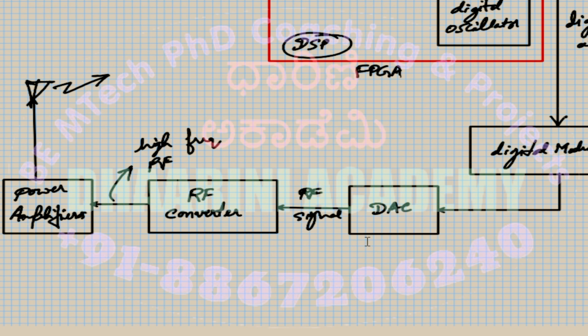If you recall, OFDM is orthogonal frequency division multiplexing, wherein you send multiple symbols, in the case of digital, over multiple orthogonal frequencies. You automatically avoid inter-symbol interference, and you can send the data faster. Parallel channels exist over there, because of which you can send it faster.